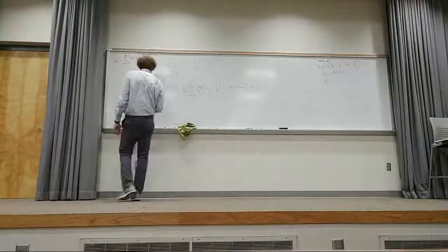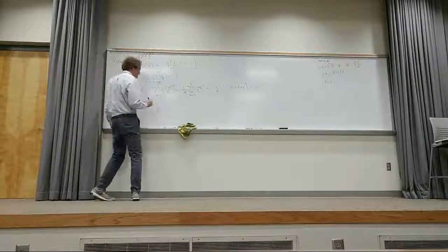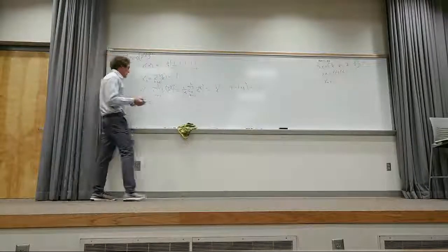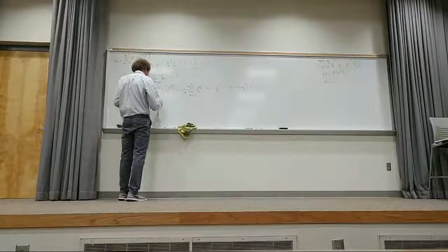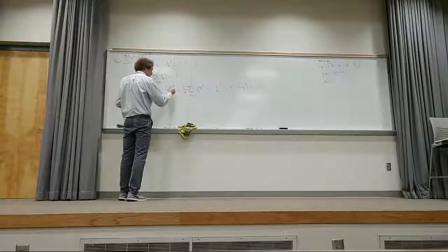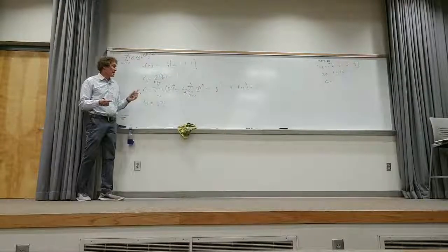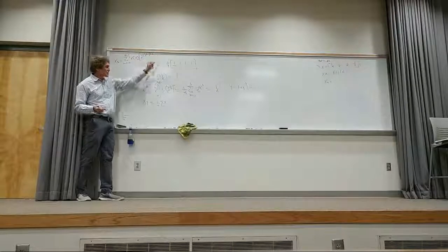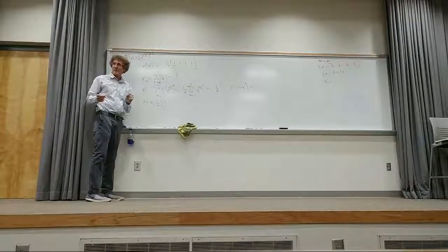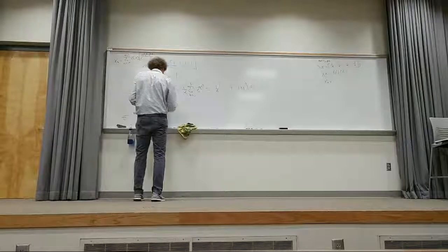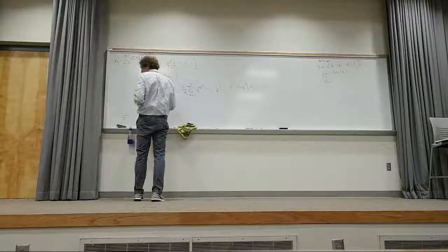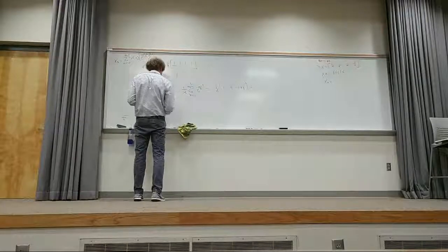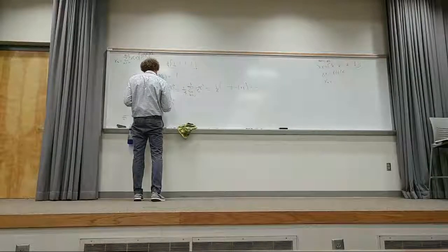What's X of 2? You can brute force it, but I'm going to show you a trick on this if I have time. Just do it. What happens? Isn't it 1/4, right? Summation of now, what is e to the minus j... now that k is 2, correct? If that's 2, isn't this really e to the minus j pi? All right, so what is e to the minus j pi? Isn't that minus 1, class? To the n equals 0 to 3.